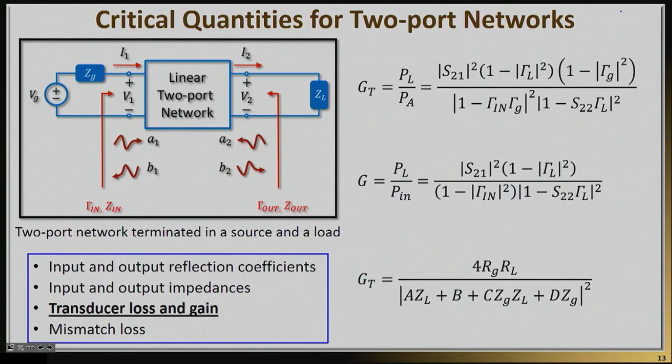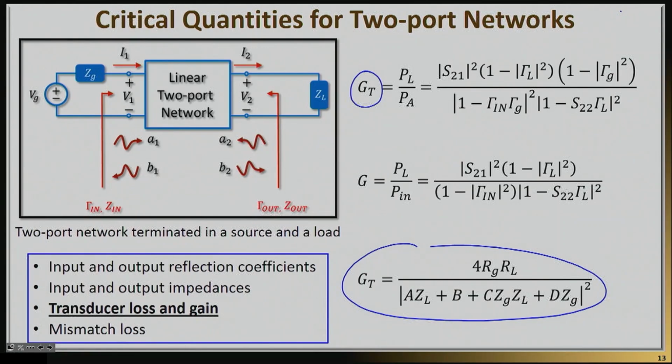Now, if you know the S parameters of the network, you can do these calculations, and as I mentioned, they're available in my notes. For example, you'll find that the transducer gain is given by this equation here, or if you will, the transducer gain can be calculated directly by knowing the ABCD matrix of the network and then knowing the load and the impedance.